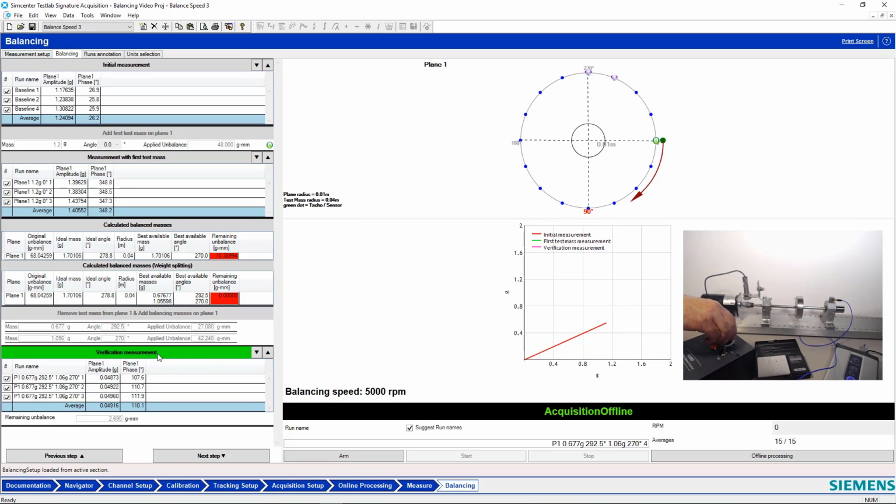So Pete, according to this verification measurement, compare that with our initial measurement. Initially, we had a vibrational amplitude of 1.24 Gs, and we've reduced that with this balance procedure to 0.04 Gs. So this accelerometer location is vibrating a lot less, which is due to the fixing of the imbalance. That's right. But we had done an order cut before, and here we just did this at 5,000 RPM. It seemed better. Should we check it against the whole speed range? Yeah, let's look at how we did across the whole speed range.